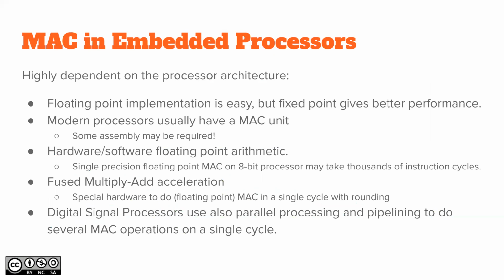Floating point implementation coding would be easy, but unless you have a DSP block or floating point block on your system, fixed point gives you much better performance.